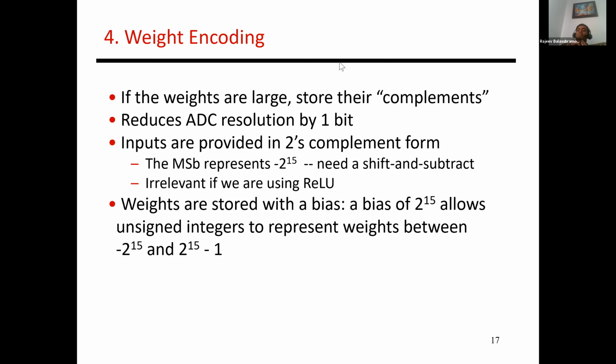Yeah, this is a point I didn't quite make. If weights depend on the resistance, does it mean that they have to be fixed in the design? That's absolutely what I'm assuming, and I'm getting to that soon. One of these crossbars is going to implement a certain convolutional filter, and each of those individual cells has to be programmed with that particular conductance, right? Once I do it, I have to leave it alone. This programming process, especially for most non-volatile cells, takes a fair bit of time and energy. So once I've programmed the cells, it's always going to be operating as that convolutional filter.